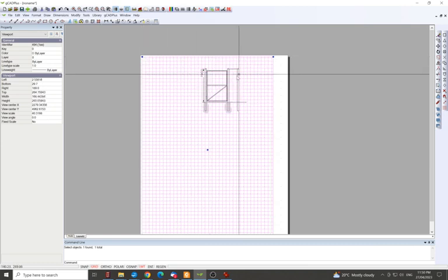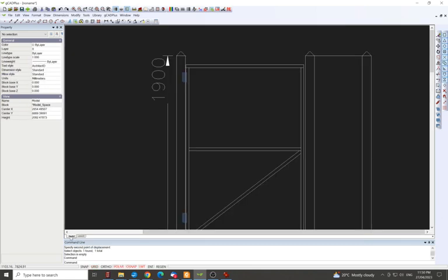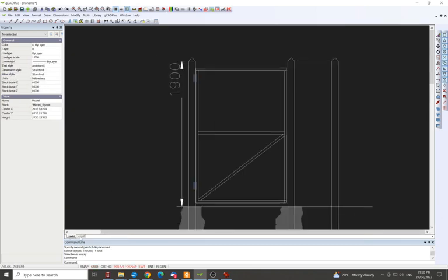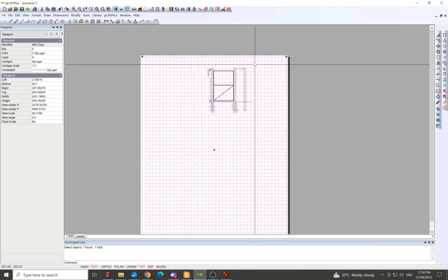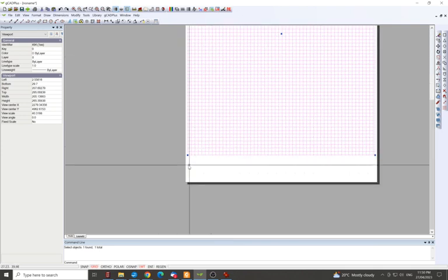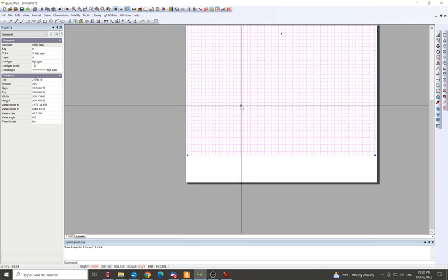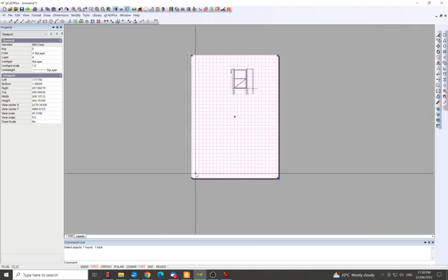And this viewport is a lens to inside the model window. So this is the model window where we're doing all our drafting. And then layout 2, we'll call it layout 2 because we deleted the first one, is what it looks like on printed paper. So this is the layout on the paper. Because we're going to open the viewport up to match the paper, and we'll just get out to that corner there, and then we're pretty happy with that because it pushes out to this A4 piece.